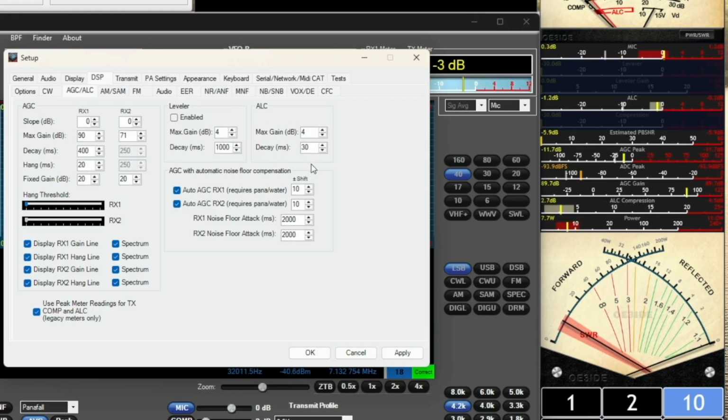There's an absolute maximum value of audio that you can send out over the air, and I can see that by this ALC compression meter, it's reducing my gain slightly now and again, which is kind of how you want it. I don't want to really heavily compress or limit the audio within Thetis itself. So they are my audio settings in the radio.